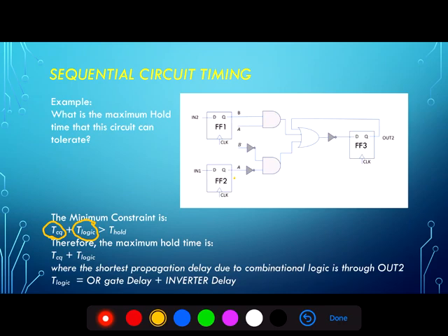For example, if we have signal traveling through here, it goes through an inverter, an AND gate, an OR gate, and an inverter. That's quite a long delay. If we look over here at B, it travels through an AND gate, and an OR gate, and then an inverter. That's 3 gates. That's a little bit faster. But now if we look at the output here,